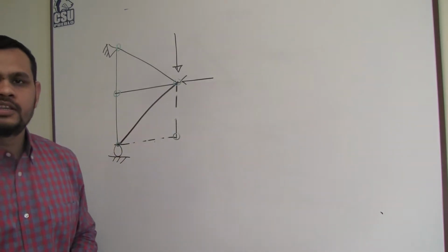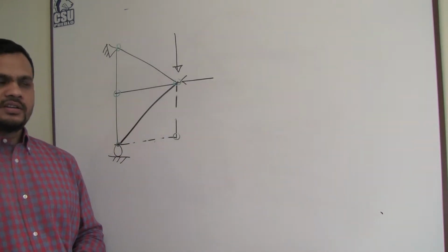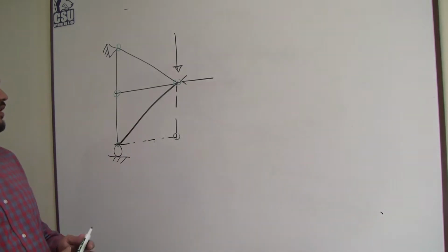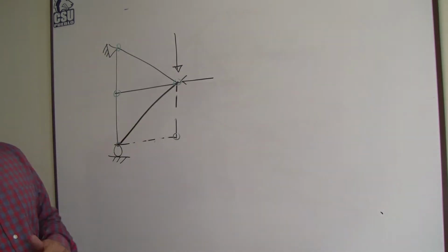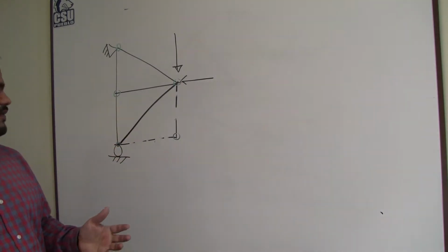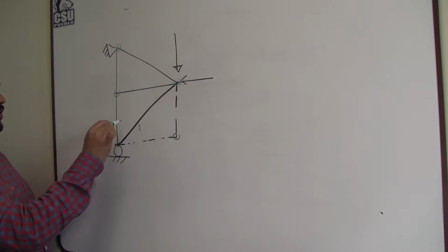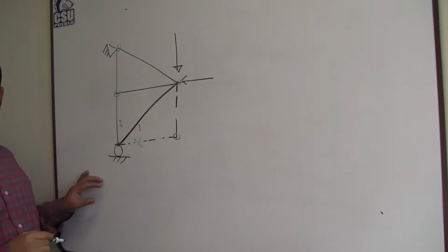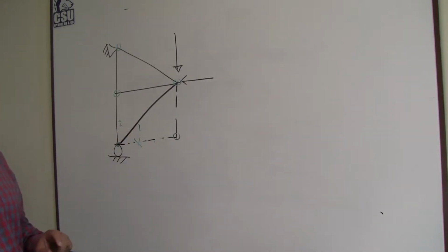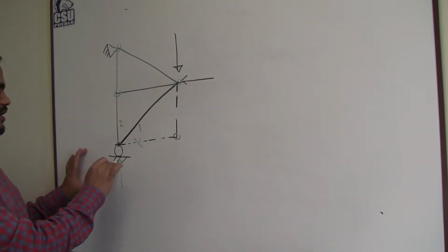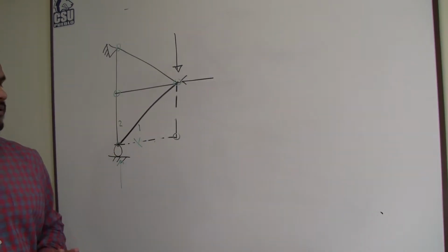If we know that this member is a zero force member, we can delete it so that our task looks easier, simpler. We can solve it easily. Then once it is done, is there any other zero force member? Here, once I delete it, only two members remain, member 1 and member 2. This is no longer available. Two members form a joint, no load, but there is a load here. This is a reaction. So we cannot decide here.